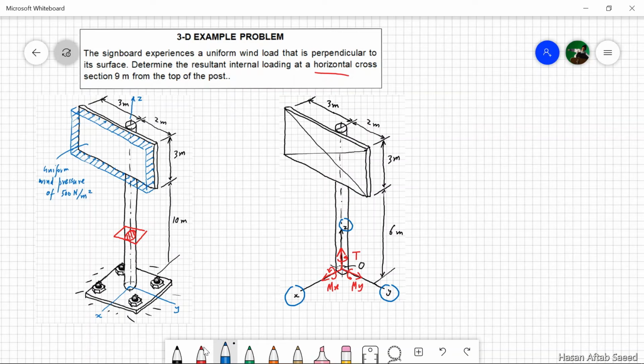And then we have three force components acting at point O of the cut section, which is the centroid. These three forces: Vx, shear force, Vy, another shear force, and N is a normal force. Point O is taken at the origin 0, 0, 0.